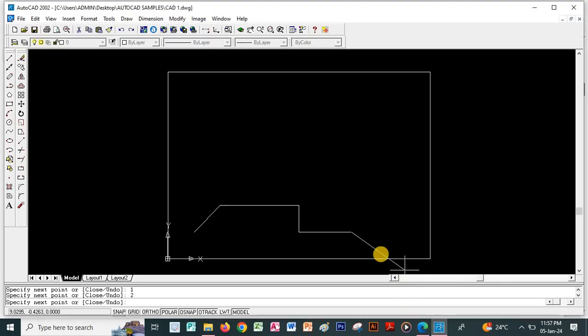Therefore we go back to our program, we click shift and 2, which is at, we insert at distance. So the distance should be 2, or the length. The length is 2, less than the outside angle, which is 45. Then we click enter, and you can see that it has inserted that specific angle.